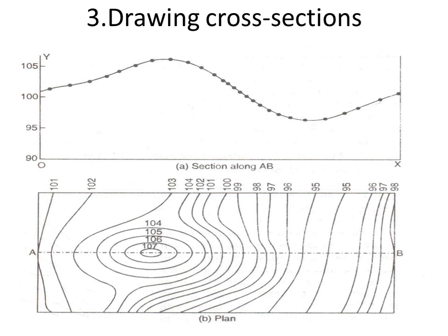Similarly, all the intermediate points are marked by taking the difference between the value of the contour and the datum, and accordingly the ordinates are taken and the points are marked. At the end, point B is also marked, having a contour of 98 meter. To locate the position of B on the cross section, 98 minus 90, that is 8 centimeter above X, has to be marked.